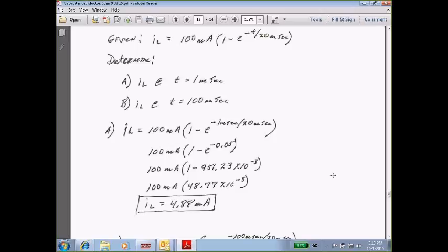Okay, when I push down on the switch, I'm applying 9 volts to the inductor and at the same time 9 volts to the neon lamp. The lamp does not light because it takes 60 to 70 volts to fire it. But when I let up on the switch, the 9 volts is removed from the circuit, so the only voltage source is the induced voltage of that coil, and the only path it has is through the neon lamp. It is enough to fire the neon lamp, and it will actually flash that neon lamp, which would represent firing of the spark plug.